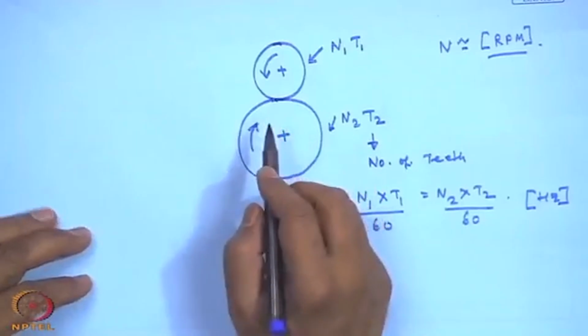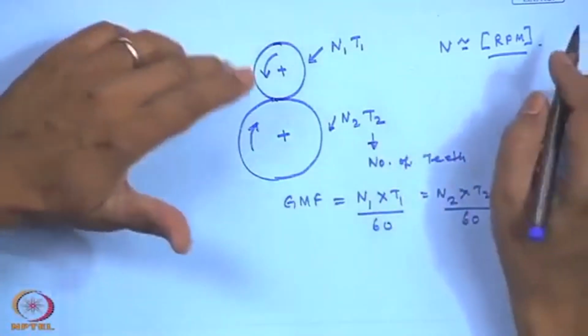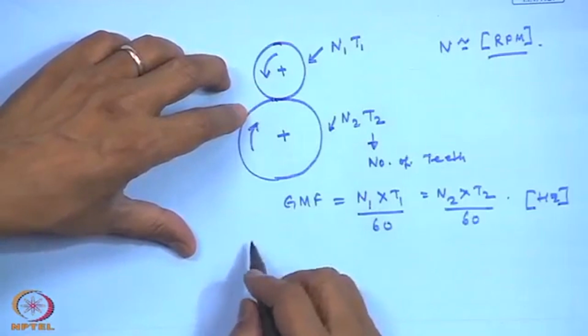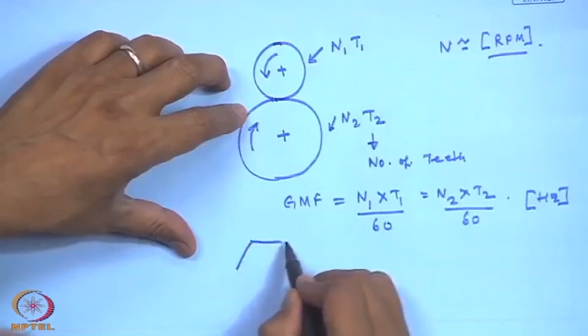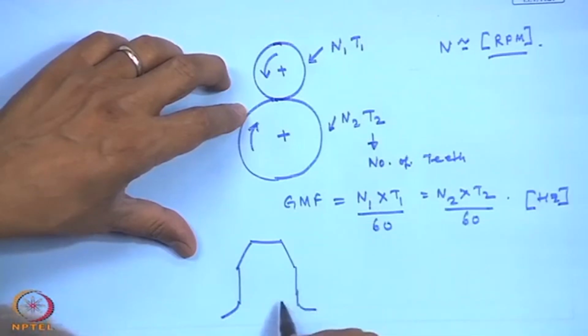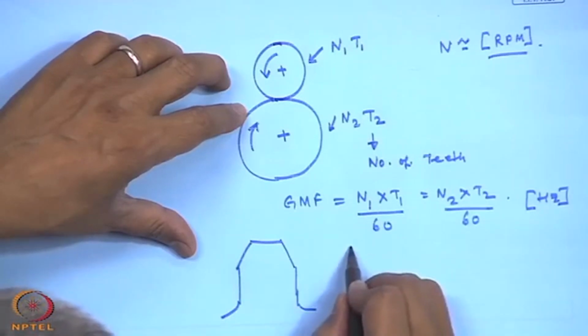So, because of excessive load, sometimes gearboxes are designed to carry a maximum load. The famous Lewis equation is used to find out the stresses at the root of the gear.